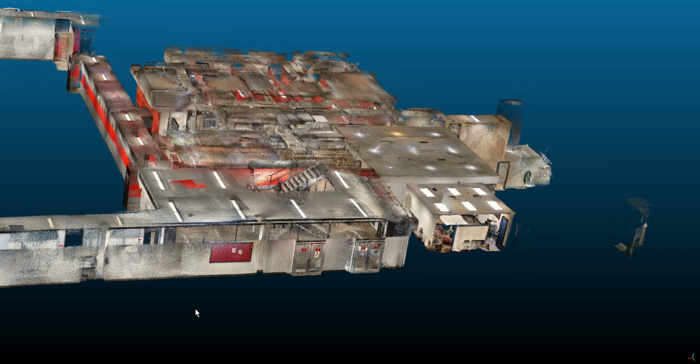To do that, all you have to do is use the translate rotation tool and fix it such that you can only move it up and down on the Z axis. I did that first with all of them. Then it made it a lot easier to merge all of the scans back together.